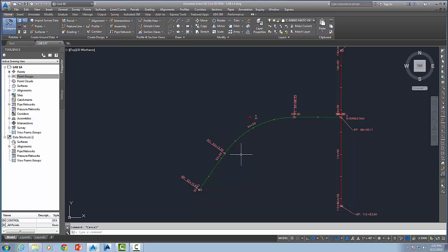So what we're going to do is just use this simple AutoCAD offset command, and you can just type in O, or you can grab it right here if it's available. And what I'm going to do is just tell it I want to offset this by 15 feet for the Township 35. So 15 feet, select my object, offset it, select my object, and show it the side.